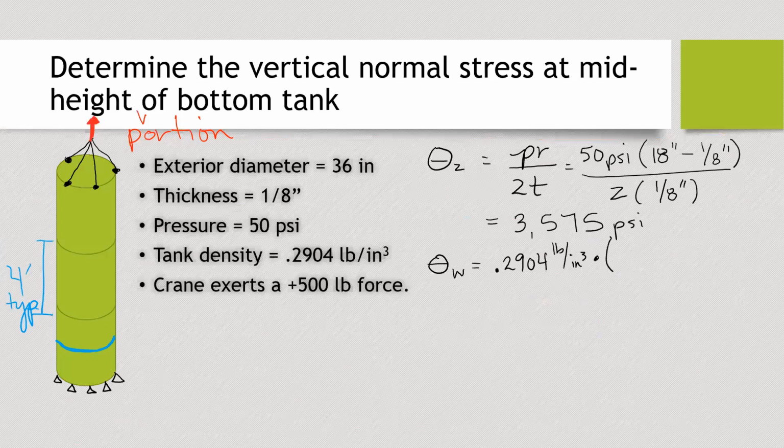So one thing we could do is take that top circle and say pi times 36 inches squared over 4. Is that the area of the top? Okay. Plus, now we have the sidewalls. So the area of those sidewalls is going to be pi times 36 inches squared minus, is it 35.75?